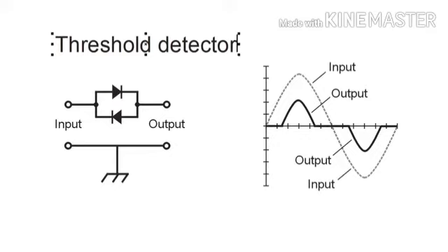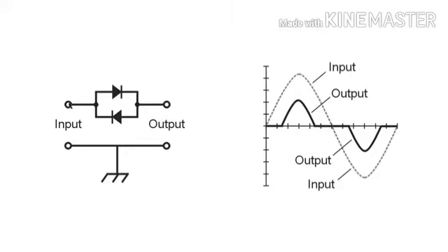Now what that will do is that if the signal voltage is less than about 6 tenths of a volt positive and negative peak, or 5 or 6 tenths of a volt, or 1 to 1.2 volts peak to peak, you won't get any output here at all. So if you're listening to a relatively loud Morse code signal and there are faint signals and noise in the background, you can in effect squelch out those faint signals. Another term for this is squelch. This is like an audio squelch.